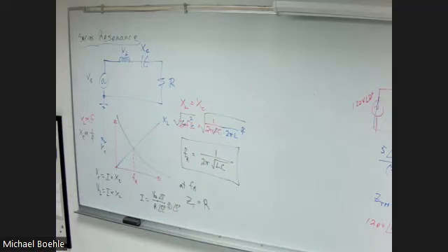And so with 0 degrees current, the voltage across the capacitor will be the same as reactance, minus 90. Likewise, for the inductor, plus 90. So the voltage across the capacitor and the voltage across the inductor are 180 degrees apart. So they cancel out.